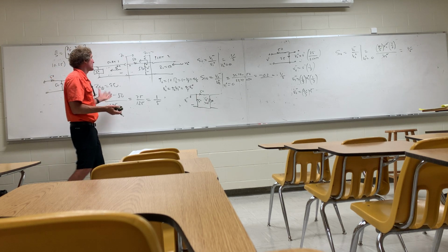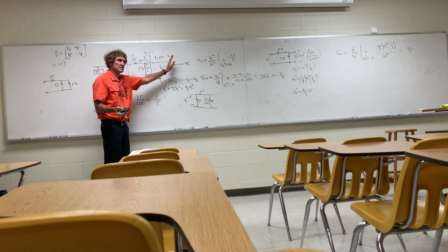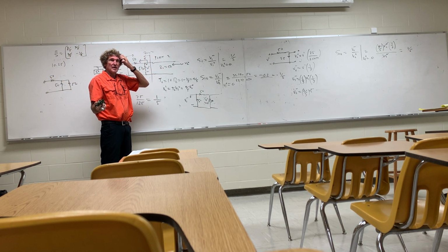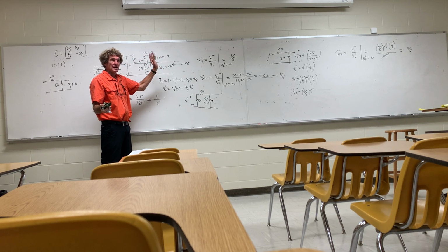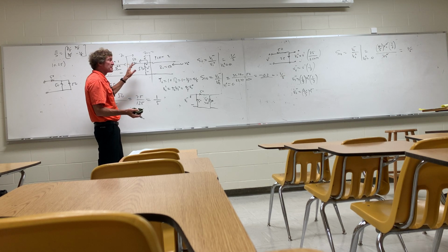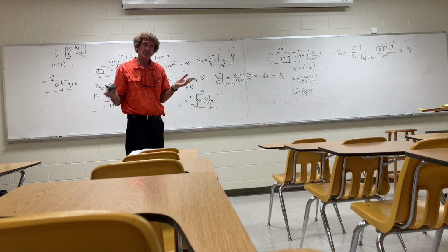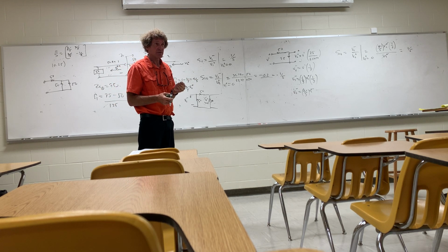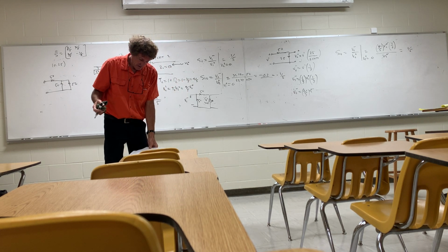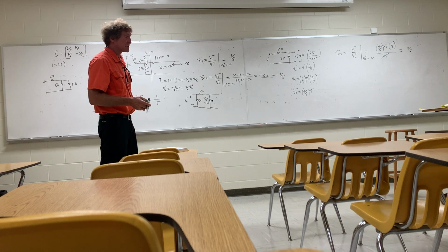I always think about it this way: if I look this way, it does not look the same as this one. It's simple. The topology is different. Now, if this had a 50 ohm resistor here, then it would be reciprocal. You know what I mean? The minute you see a resistor, it's not lossless. And there are plenty of them. Okay, so that's that problem in a nutshell. Did that help at all?